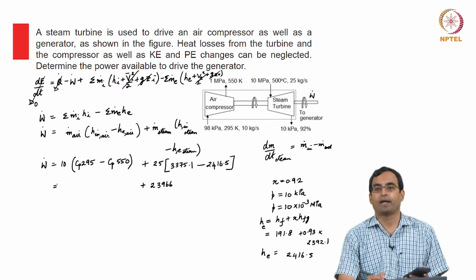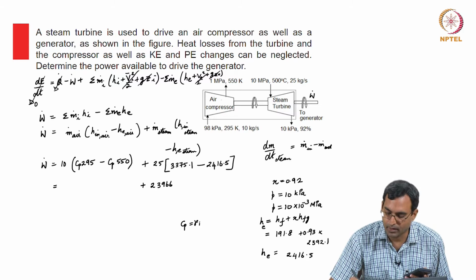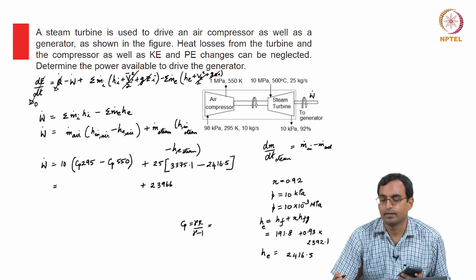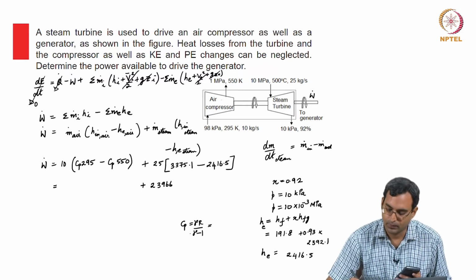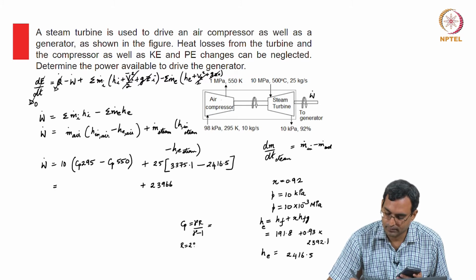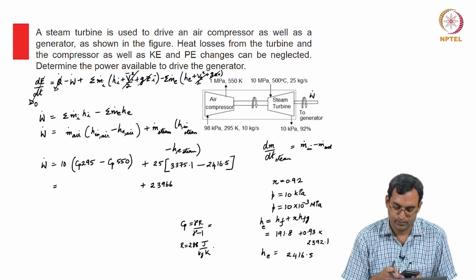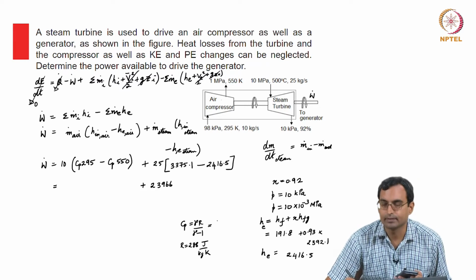I need the value of Cp of air. So, Cp of air is gamma into R by gamma minus 1. I need the value of R. We have calculated this earlier as approximately 288. So, if I take R as 288 joule per kg Kelvin, so I get 288 into 1.4 divided by 0.4, which gives me a value of about 1008 joule per kg Kelvin.